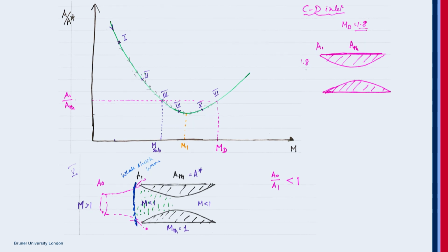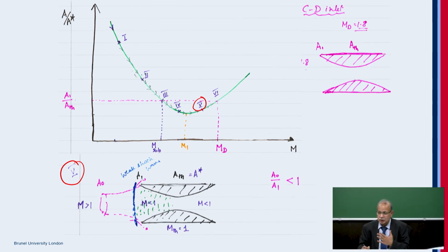Now we have just come to station 5, low supersonic regime. We have gone through this transonic regime. Now the aircraft has gone into the supersonic regime. The pressure waves coalesce. One of the things we'll be looking at is that the pressure waves are very unstable in the converging part. So they are all being pushed up, they coalesce to form a weak shock wave in front of the inlet. Now you can see, as I said this morning, that there is some spillage of air taking place.